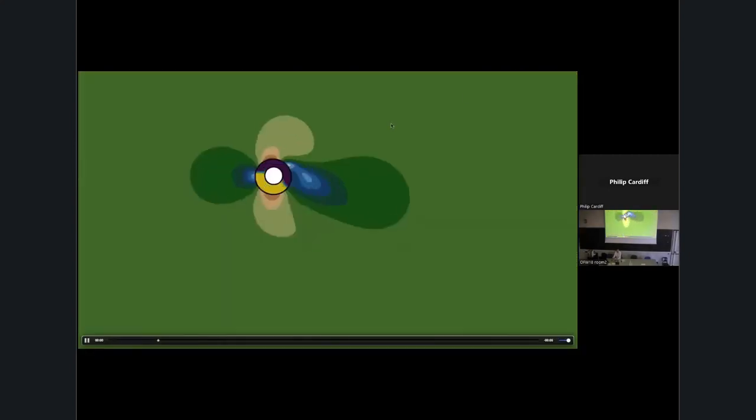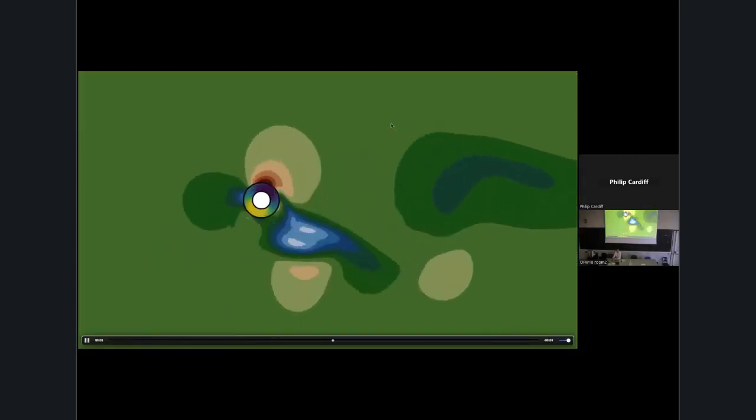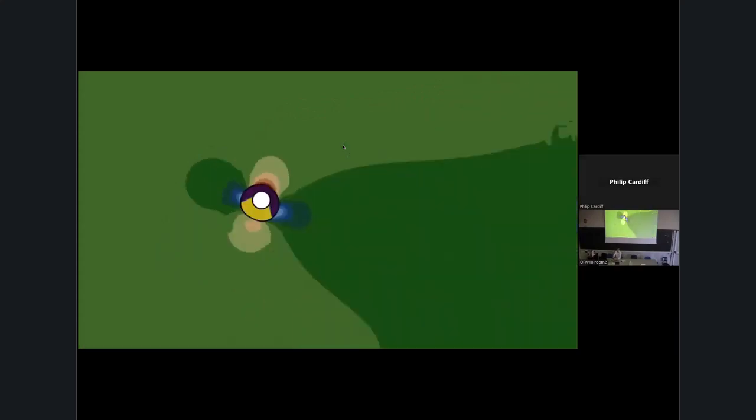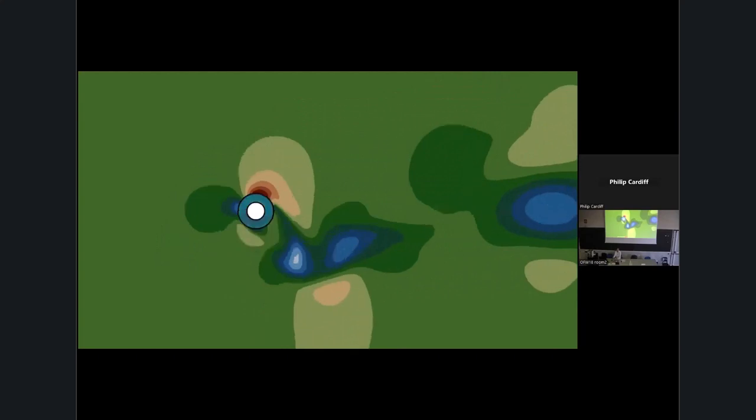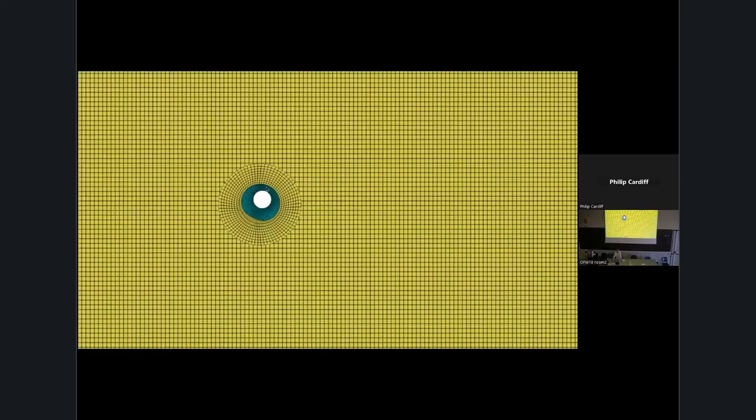If you run this case with some artificial properties, I'm moving it back and forth so you can see the little rubber donut bouncing around essentially. Because it was imported, this was actually using preCICE to do the coupling. This tutorial you can find on the website, and you can define it in solids4foam. At a particular snapshot of the deformation, you can see that the solid is deformed and the overset region is tracking it, but the overset interface is just zero gradient, it's just rigidly moving basically.